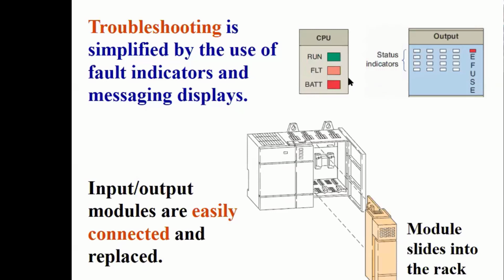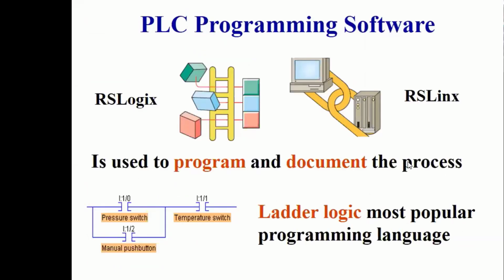Such as when the controller is faulted, or when the battery has gone bad. I have gone to places where a machine has stopped essentially because power went out and the battery of the PLC went out too. And so you just replace that. They don't run out very quickly, but something like that could happen.